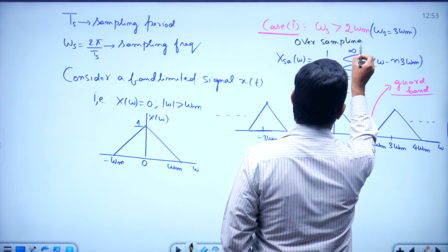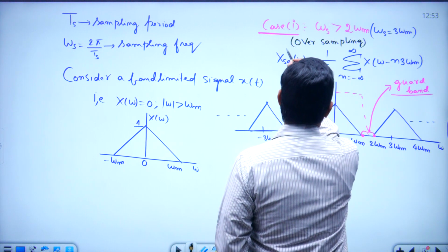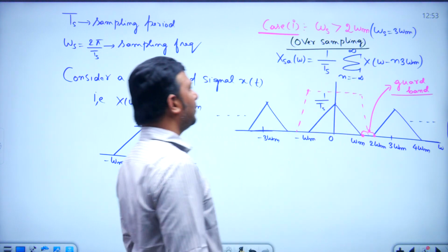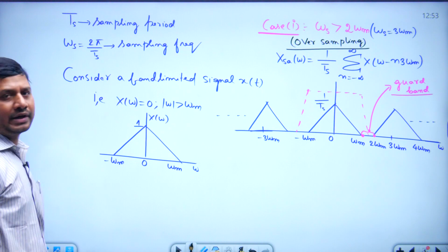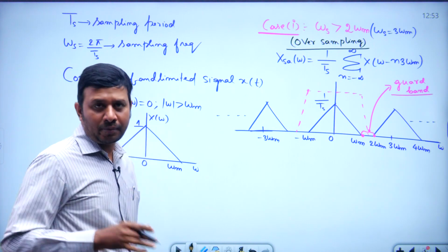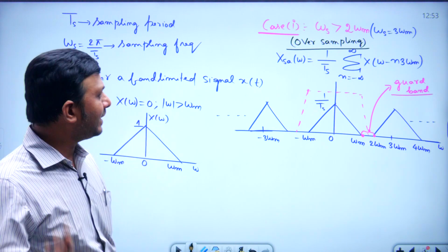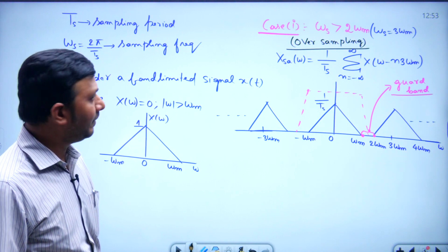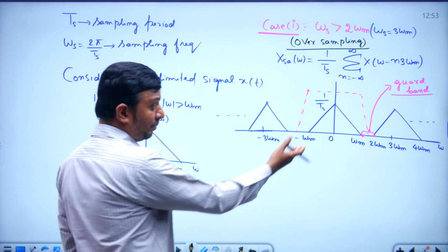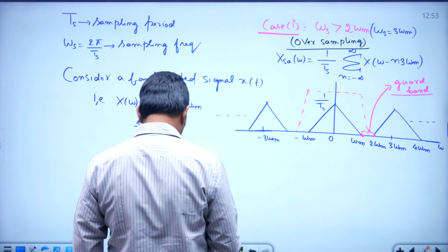So observe here, omega s is greater than 2 omega m, no problem. Yes, we can reconstruct the original signal, and there is a provision of guard band also.